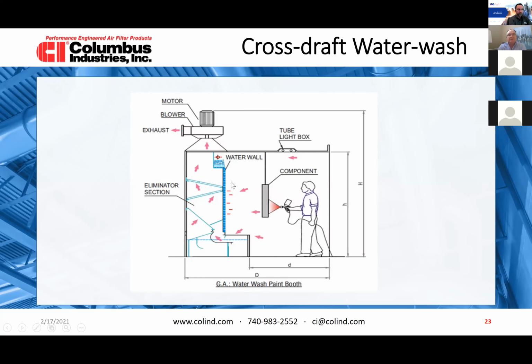But with the quality of the water, with the scale that you might find in the water that could be deposited on the stainless steel walls, you might have some openings in that curtain. And therefore, when you have an opening, that means you have exposed metal, and the particle would hit right here coming in with the speed, and then it would bounce back because the water didn't take it down like it's supposed to.